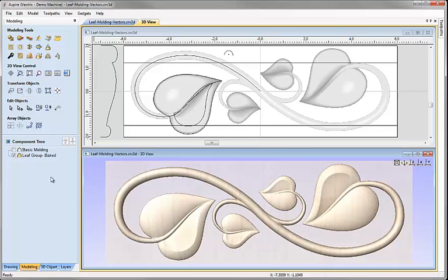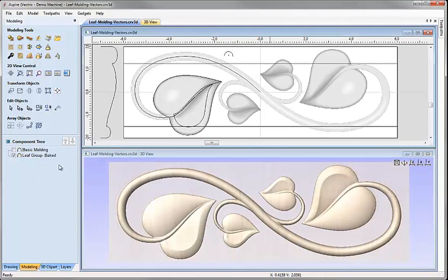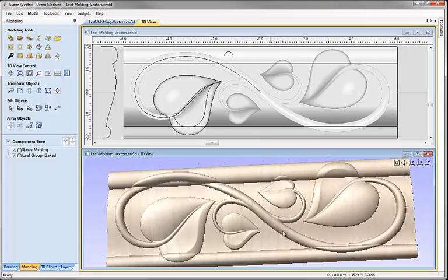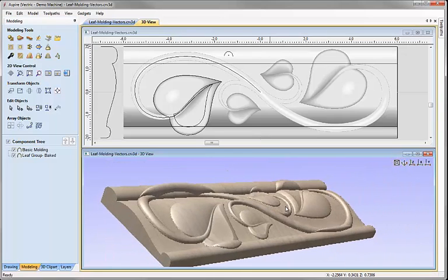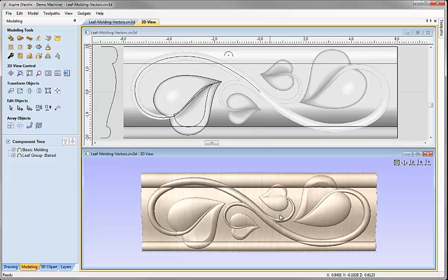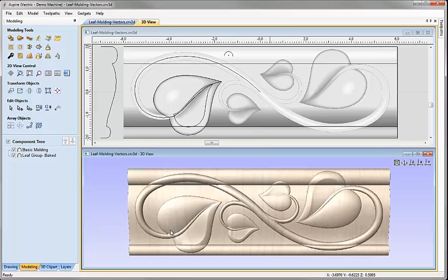Now what I want to do is think about how we can combine that to get it to flow over the top of our basic molding shape. If we switch on the molding component, we can see how those two are being added together. And that looks fine, apart from the areas where we've got these heavy creases which are being transmitted through into the leaves as well. So what we need to do is create a shape that the leaves can go on, which is smooth but still quite closely follows the profile of the moulding vector.